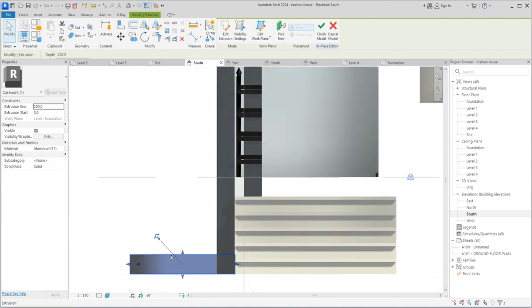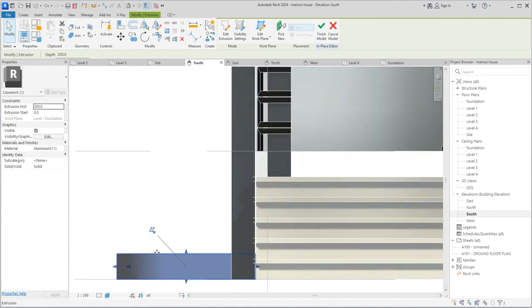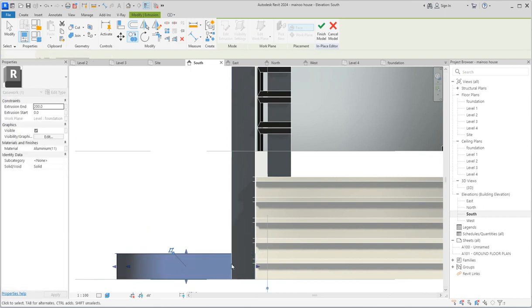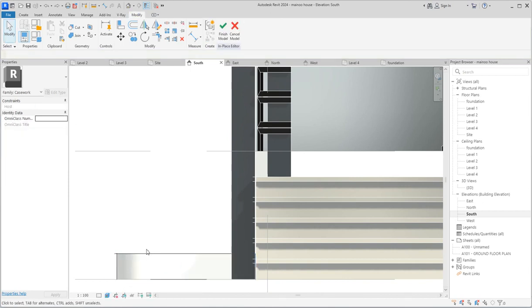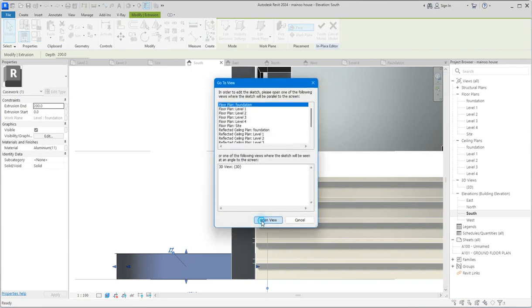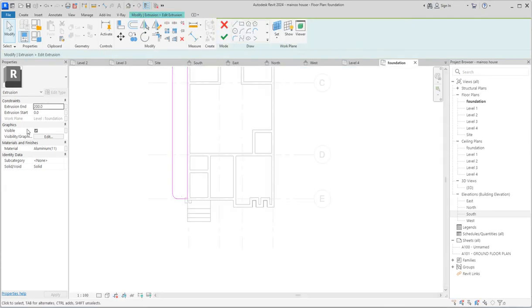What I do here is that I want to click on this, to select this and say pick. So say copy from here, copy it to 1, press 1. If you press 1 now, you can reduce this. You see how they turn that into that position. So press Ctrl Z, select any one of them and say extrusion, go to foundation level and open it.